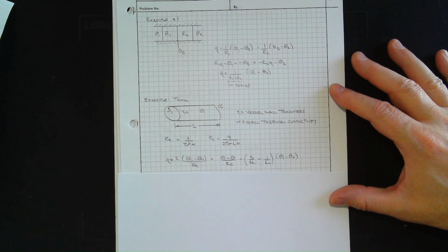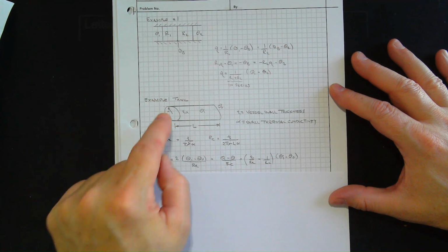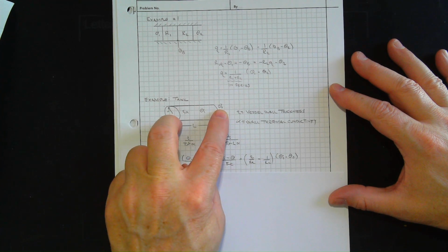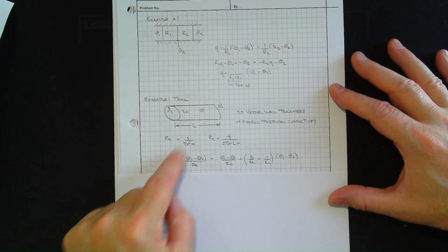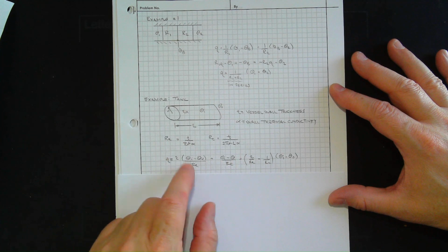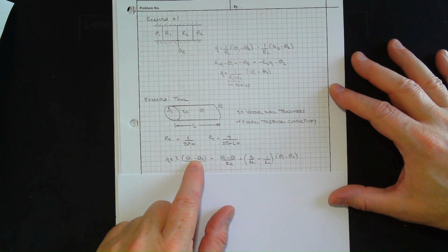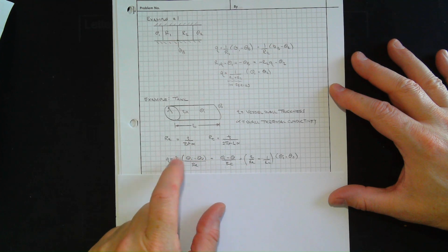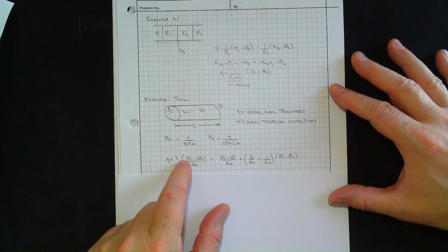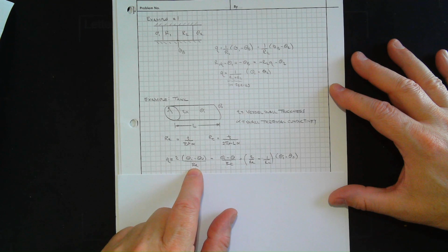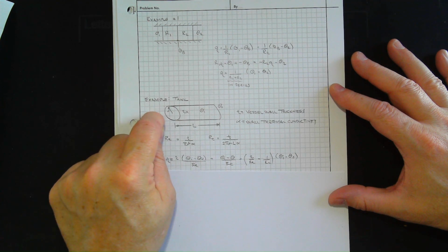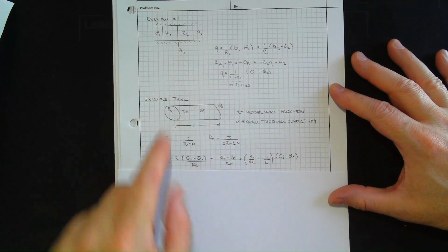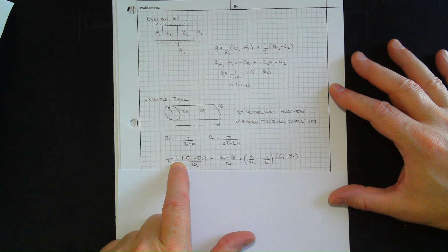All right. So how does heat leave? Well, it actually can go out through both ends and the walls. So we'd have the total heat leaving, assuming it's hotter here than it is there. You have the temperature difference that drives it, and then I have two resistors. So we have theta I minus theta O divided by the resistance of the end, which would be the heat flow out of one end. Then the heat flow out of the other end, we just multiply by 2.